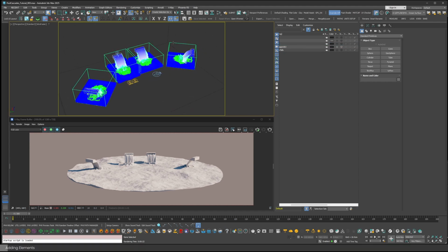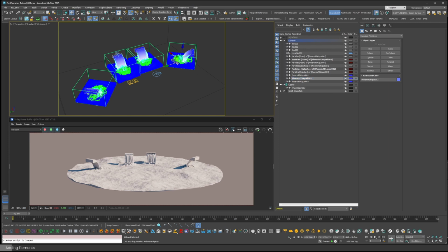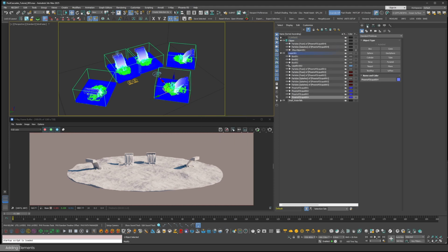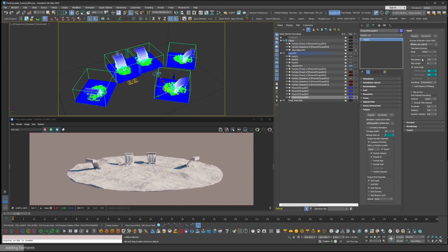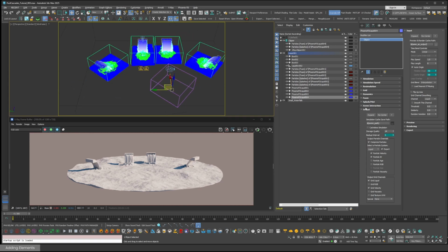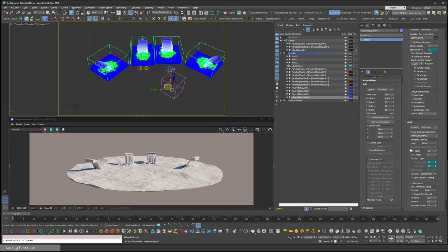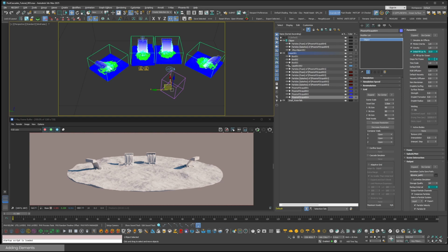And let's add another element. I'll get one of these grids and copy it over here. Perhaps it would be better to set up one from scratch, but this video is already too long, so I'll use the settings from one of the grids I already have. I'll just reset the path because I want to write another simulation sequence. Right, so now it is empty. I'll change its dimensions. 90 by 90 voxels might be good. I'll keep the same height, because I want to use the same level of the ocean fill.